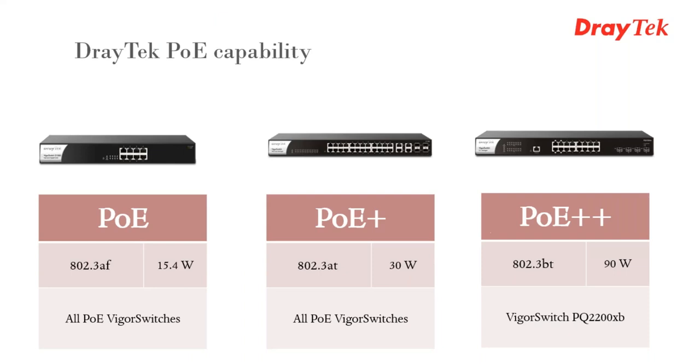So we've got the PoE standards supported on DrayTek switches, starting with PoE, or 802.3af, which supports up to 15.4 watts per port. This is available on all Vigor switches. And then the PoE Plus standard, supplying up to 30 watts per port, also available on all DrayTek PoE switches. And then we've got PoE++, supplying up to 90 watts per port. This is only available on the PQ2200XP switch.